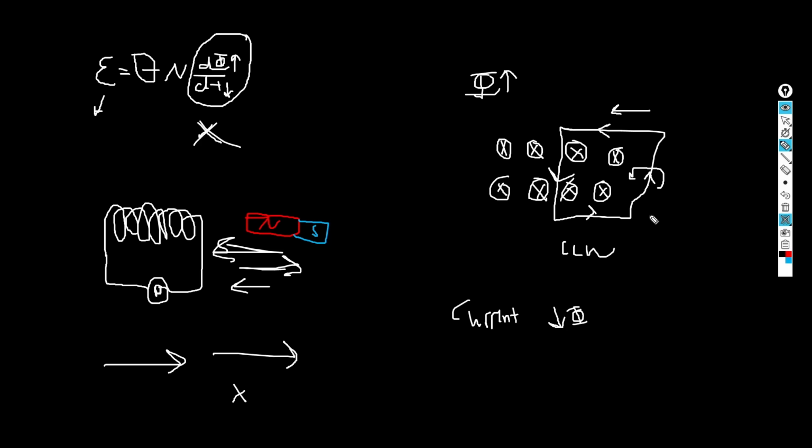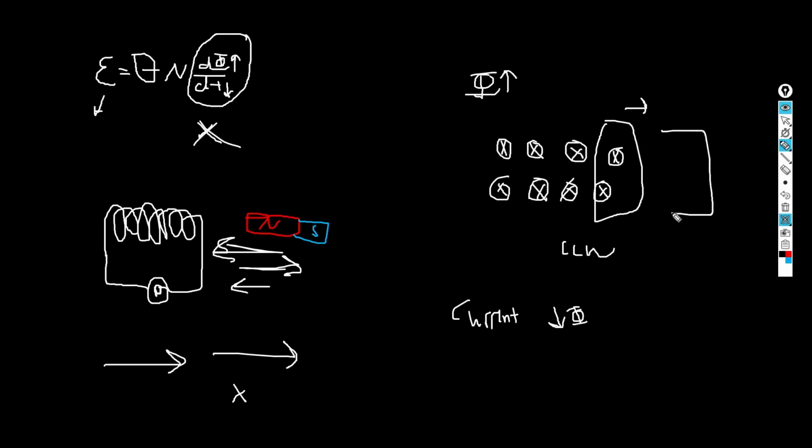Okay. Now let's say another case. Let's say you try to pull the wire out. Let's say this is the wire naturally. Okay, wait, let me erase this bit. I hate how it erases everything I write when I use erase. Let's see here, and you move the wire this way. So now there's no magnetic field in the wire. You moved it out. So phi in this case decreased. So the current would want to increase it. It's opposing the change. Opposing the change here, negative.